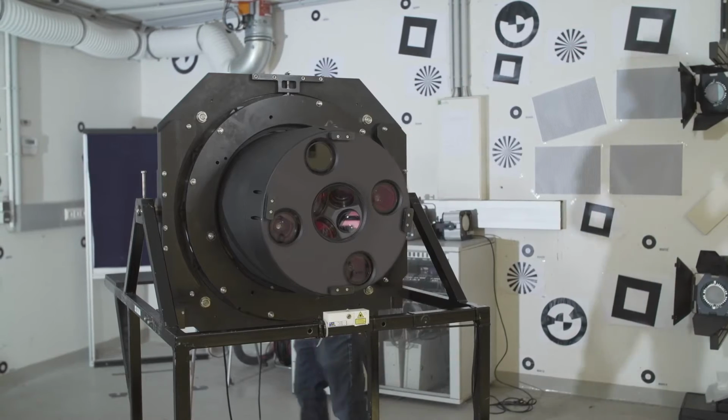The nadir footprint is determining the flight efficiency of the camera system, and here the UltraCam Osprey 4.1 has a really impressive footprint size. The footprint is more than 20,000 pixels wide across the flight strip and more than 14,000 pixels wide along the flight strip. And that gives an utmost flying efficiency for this camera system, which is in the league of large format camera systems.